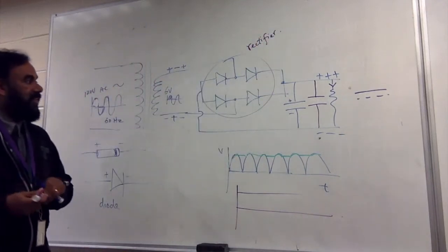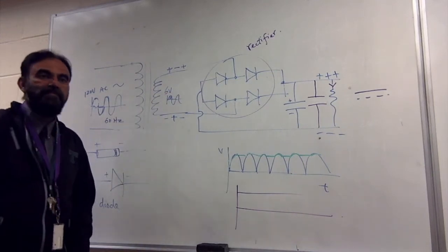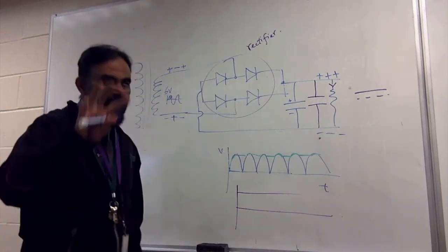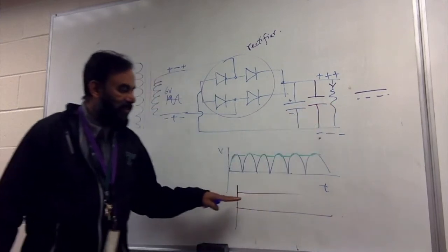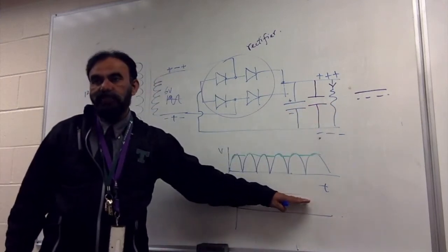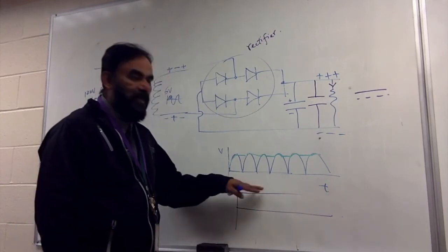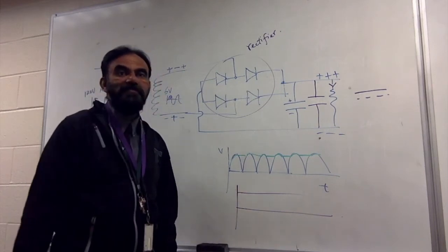It rectifies AC to DC. It's called a rectifier. So that stage is a rectifier stage, which is the 4 diodes, and this is basically the filtering stage. And once it's properly filtered, you get a very good output. So if it's a very cheap adapter, you will still get a bumpy output. And those bumps are called ripples.